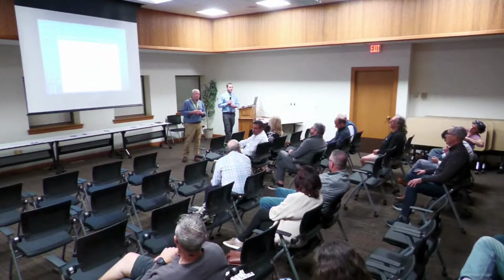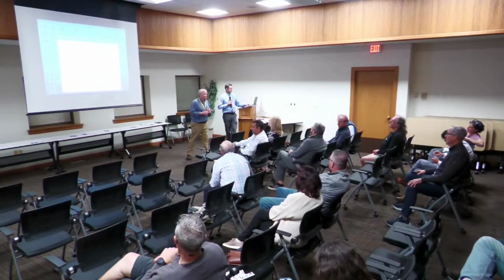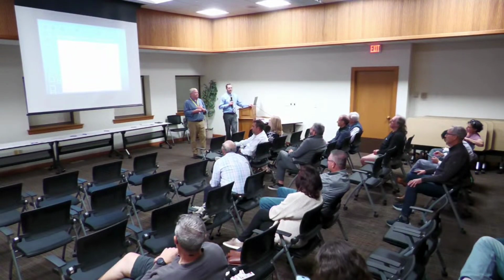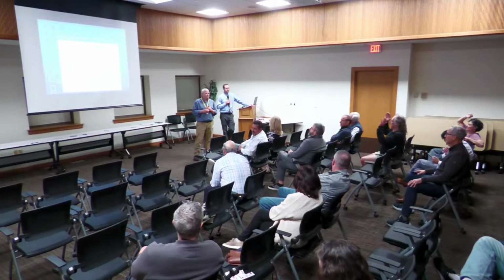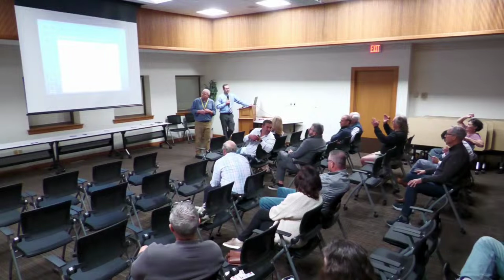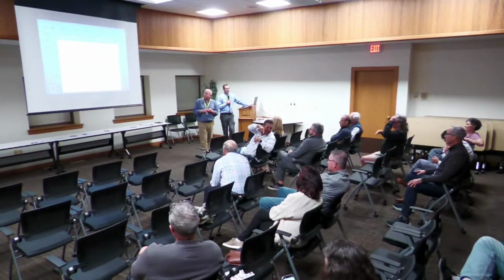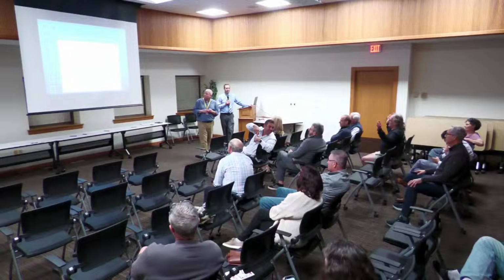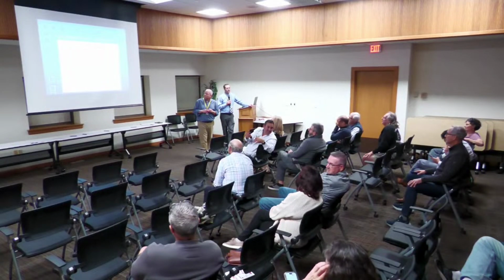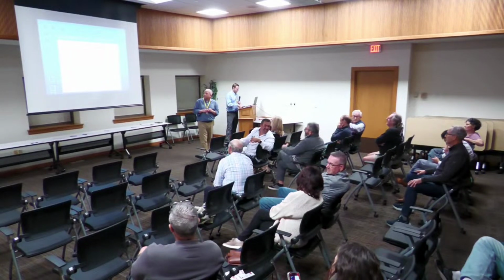As a resident, I want a light there. I want to stop right there. I don't know if that's possible. For an intersection like that, there are certain warrants and criteria that need to be met in order to establish a traffic signal, and based on the volumes, it wouldn't be warranted at that location. I think it's harder just because it's angled.